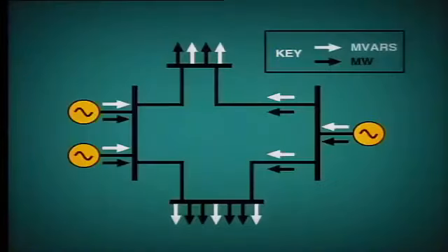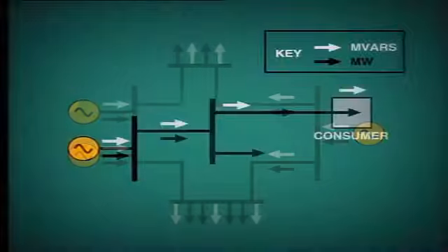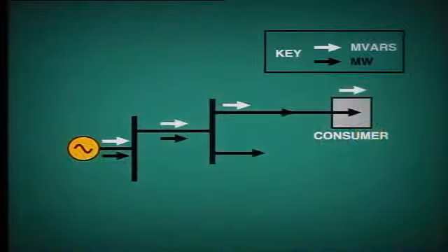So on our power system, we have a demand not only for active power, that is megawatts, but also for reactive power, or megavars, and both of these power components must be supplied by the generators. Fortunately, the provision of megavars does not require any increase in energy input to the turbines. The fact is, reactive power does not absorb any energy at all.